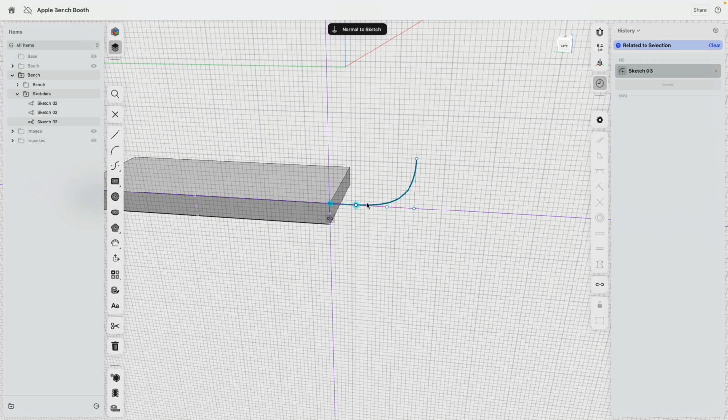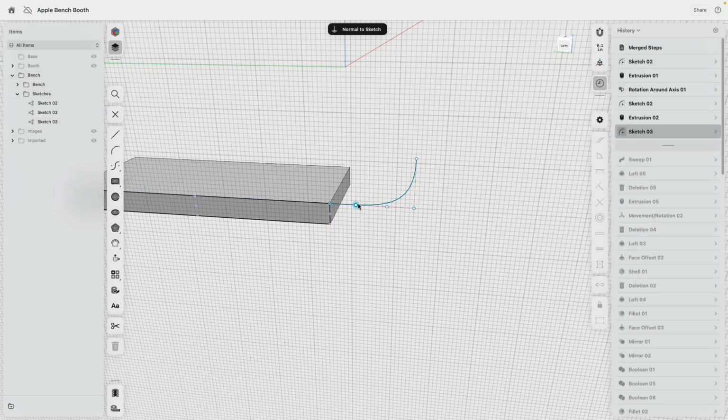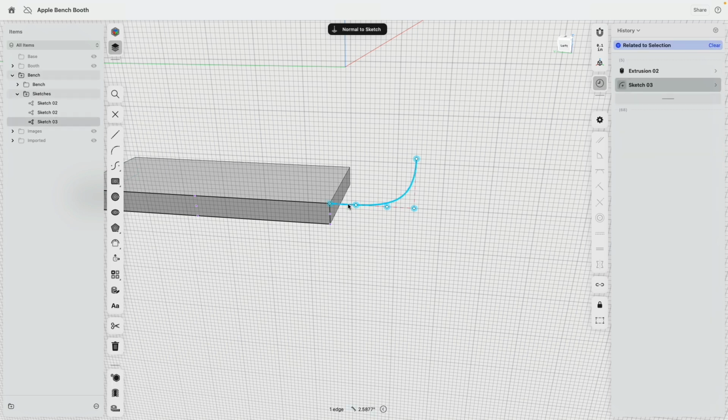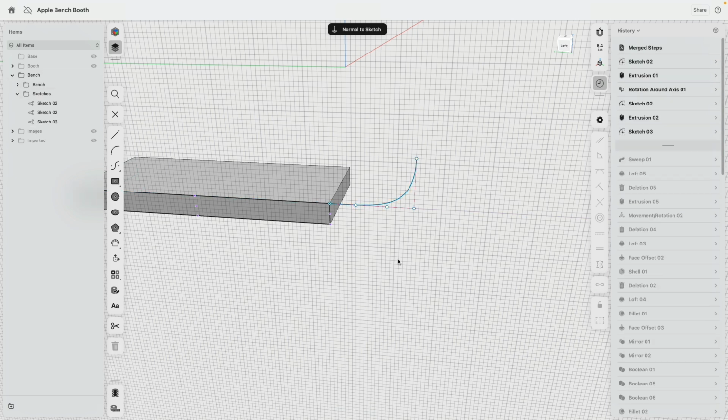The point is 1, 2, 3, 4, 5 control points with the control point spline. And these points all have to be essentially on the same line like this line. So we get a curve that is G3 to this line, super smooth.